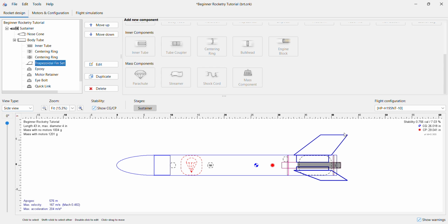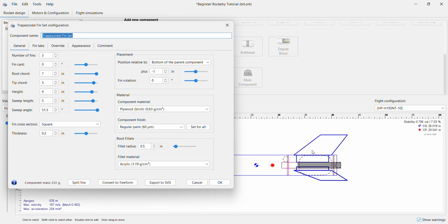There's going to be a stress concentration. There's going to be a lot of forces right here, and it might crack. So we do want to strive away from this design. It's not like it's not a valid design if you do it correctly, but we want to strive away from that.